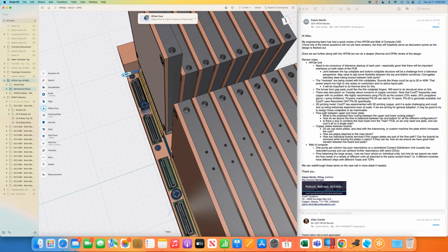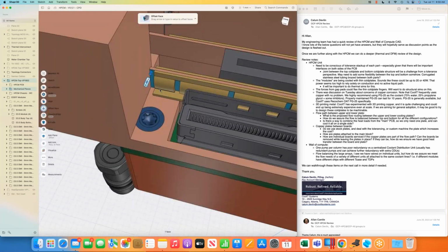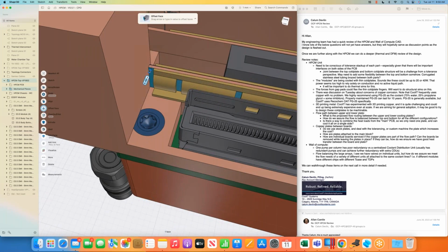But the extra millimeter will give us a little bit more thermal mass on this copper lid for conducting the heat down. But we didn't extend the gap. We kept it at 9.3 millimeters because we're not blowing air through this. But as I built this thermal structure up, I realized that we were just being left with a hair's breadth of copper here.